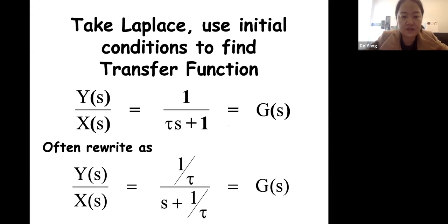The sensor problem is still a typical first order response, which means we have the typical transfer function for the first order response, Y(s) over X(s) equals 1 over tau s plus 1, which can also be written as G(s). Remember when we introduced the closed loop diagram with the notations of G's and H, this G(s) is one step in that closed loop control.